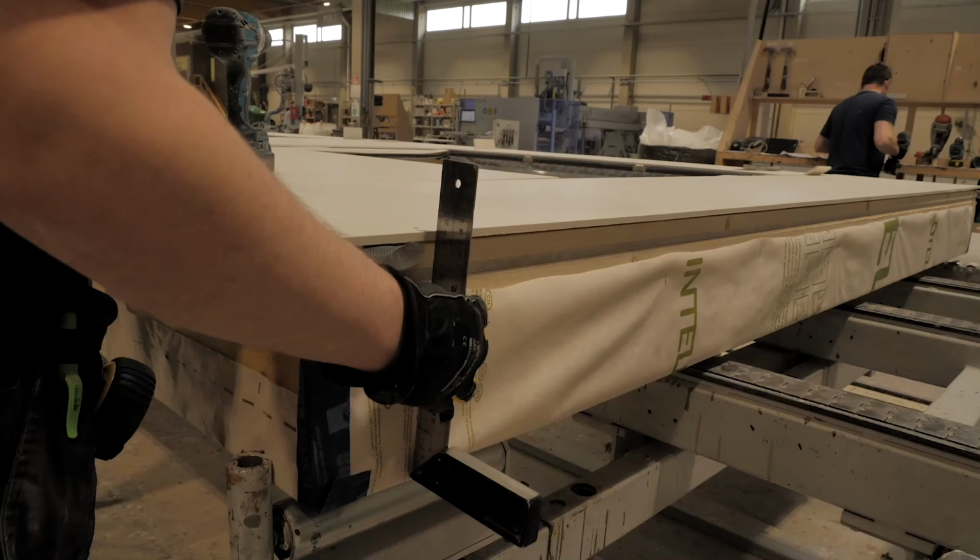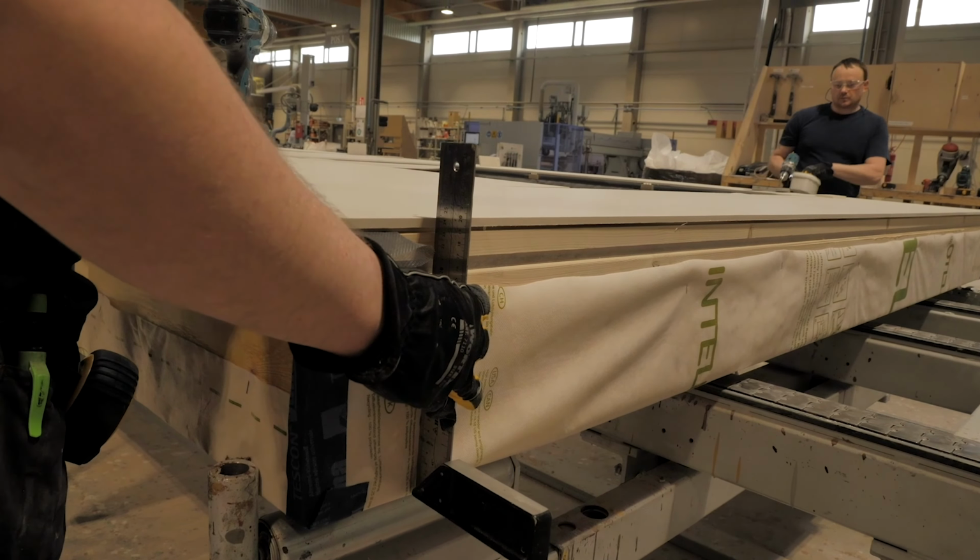First, make sure the facade panels are cut to the required size. Align the panels on the element and start fixing them. Ensure the panels are symmetrically aligned and the gaps between them are consistent. You can use special boards to ensure the gaps between each panel are exactly the same width. With the element nearly complete, only the windows and compensation wool need to be installed.